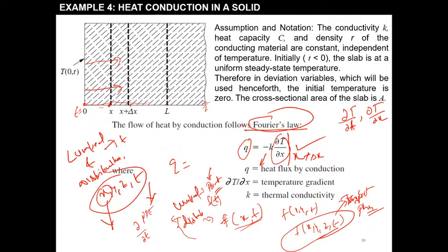Am I audible, sir? Okay. So therefore, this problem becomes a distributed parametric model problem. Now, the lumped parametric model is a simple differential equation, d by dt. However, in the case of the distributed parametric model, the model will generally give a PDE, a partial differential equation.